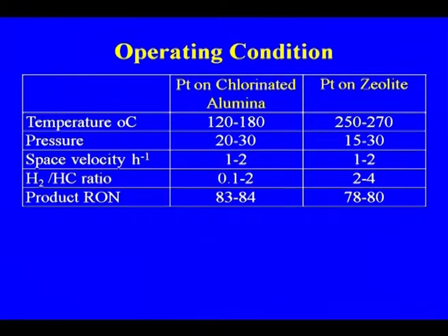Operating conditions depend upon the type of catalyst you are having: the temperature range changes, pressure, space velocity, hydrogen to hydrocarbon ratio and the product research octane number. Depending upon the type of the catalyst, there are slight differences in the parameters.